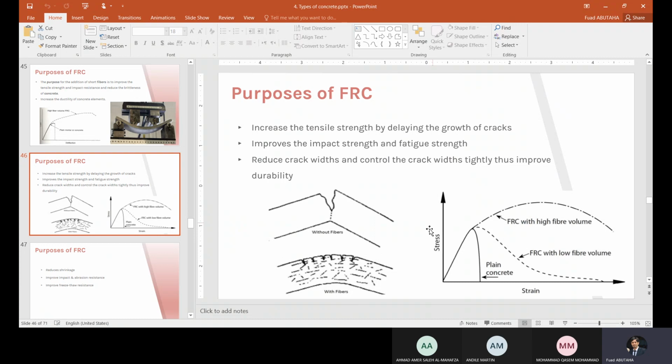And you know the stress strain diagram and the failure behavior of the concrete is brittle. Actually, it's different. Concrete is not a ductile material. It doesn't show any deformation before it fails, like steels or any other material that shows deformation, plasticity before it fails. It's simply a brittle material. It fails directly, sudden failure.